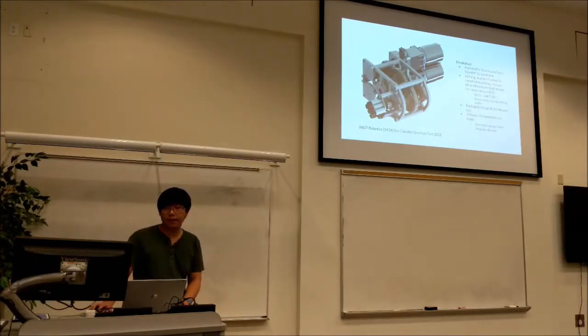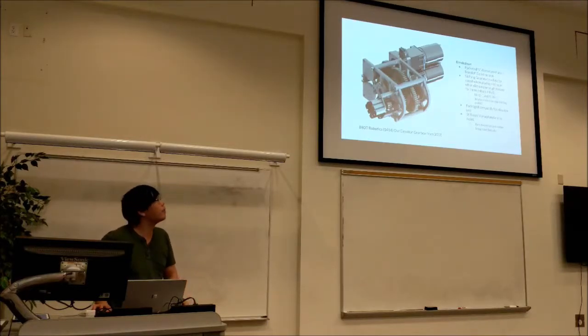So this gearbox is designed to allow us to shift, so we can carry 3 robots with us, plus the factor of safety. Also, you'll notice how we still use versaplanetaries, right? So even though it's a custom gearbox, that doesn't mean you can't use a versaplanetary as an input. The reason why we did this is just to have modular gear ratios, so we could change the gear ratios easily, and also use the integrated encoder for the versaplanetary.